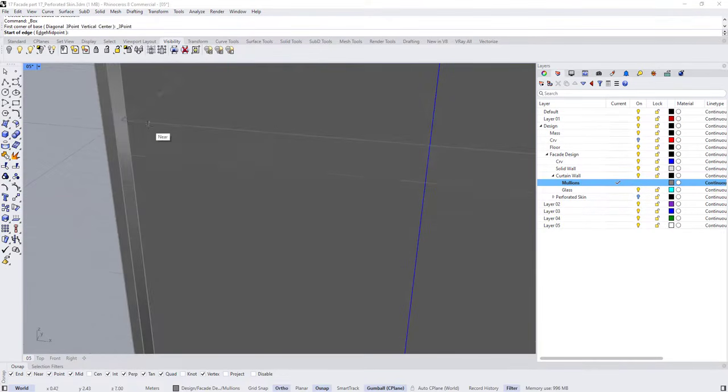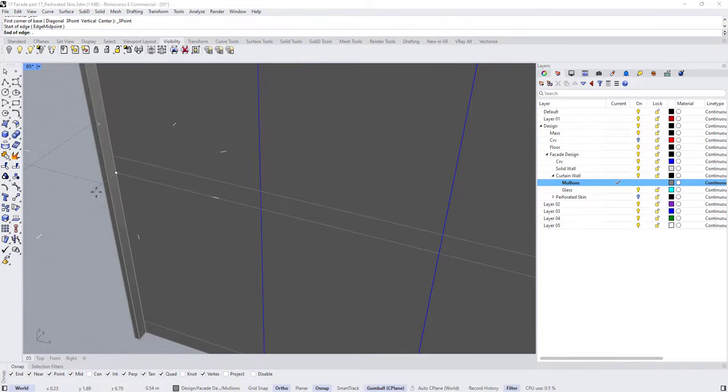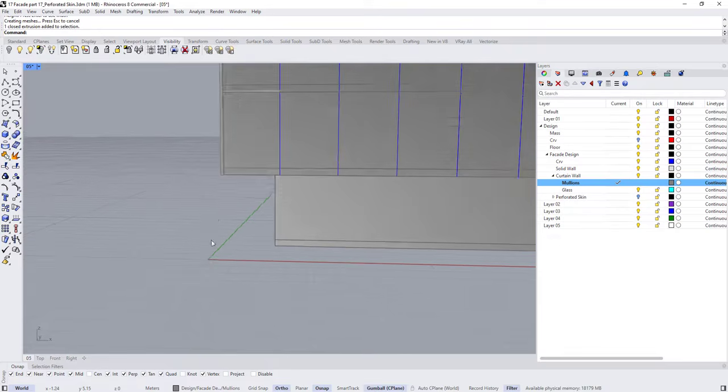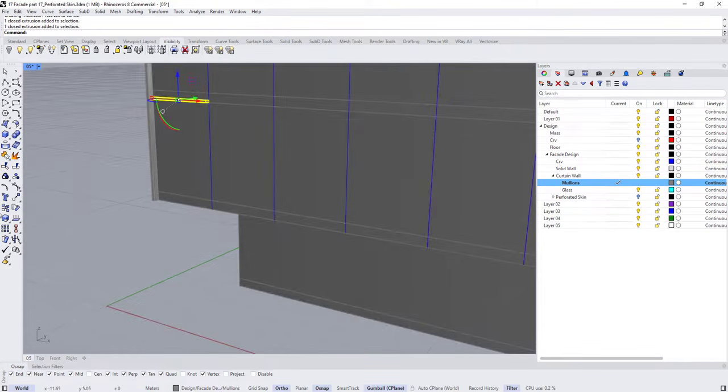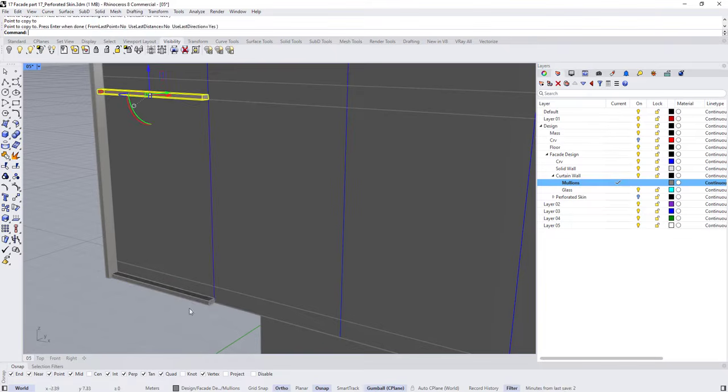So in the same model layer, I'm going to create another profile, snap here in the intersection, and set the length to 0.15 and the width to here. And the thickness 0.1 maybe, 0.08, something like this. Choose move vertical and move it down like this.